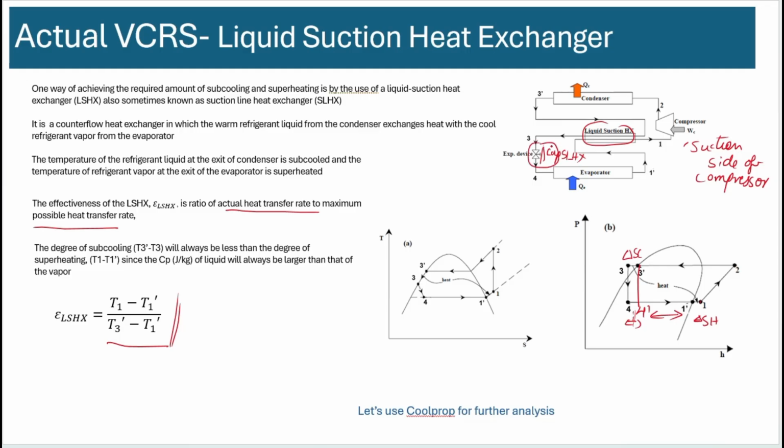So you can do a heat exchanger here or here, whichever way you cool it, and you bring it further towards the left such that more liquid comes to the evaporator, you're increasing the cooling capacity of the evaporator. And that is always done in all the commercial refrigerators and air conditioners to gain this free efficiency. Okay, you don't have to do extra work. You just have to add a heat exchanger, and you can reap the benefits from that.